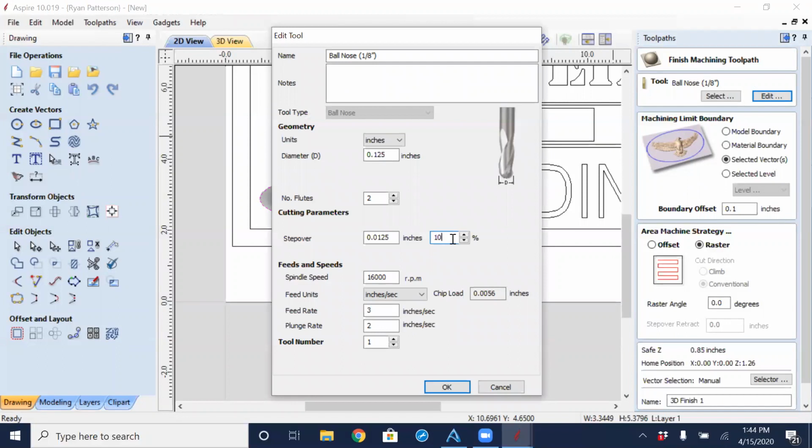And I also typically like to have my feed rates for the X and Y to be the same. The reason for that is all 3 axes are going to be moving at the same time. And having them set differently is kind of like running a 3-legged race. If I'm running and teamed up with an Olympian runner, and I tie myself to his leg and we're off for the three-legged race, does not mean we're going to win. The only thing it means is that I'm going to slow him down. So that's what's happening here.